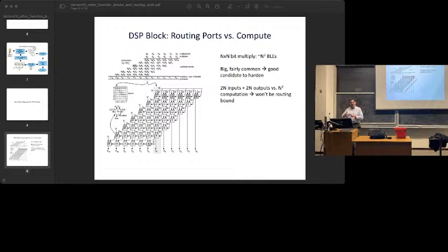I have young daughters, so I've done this more recently than you maybe, but that's what you're doing with pen and paper. You probably just don't do it in binary. So you get a whole bunch of AND gates, and then you have to add all these bits up, so you have a whole bunch of adders. That's basically how a multiplier works.